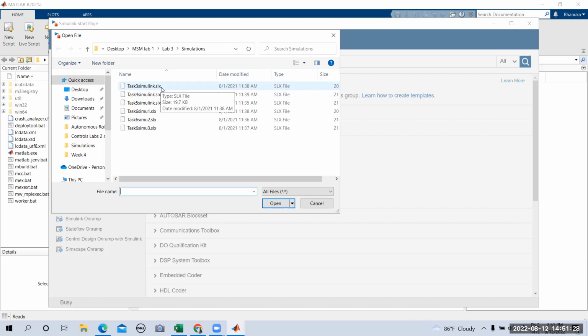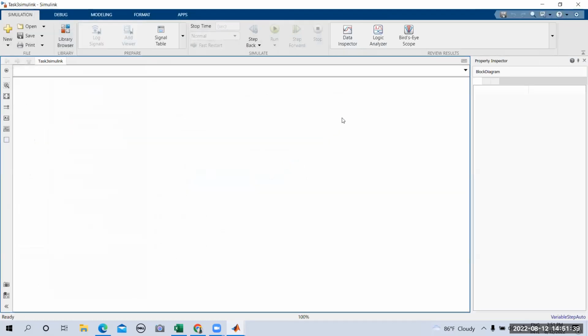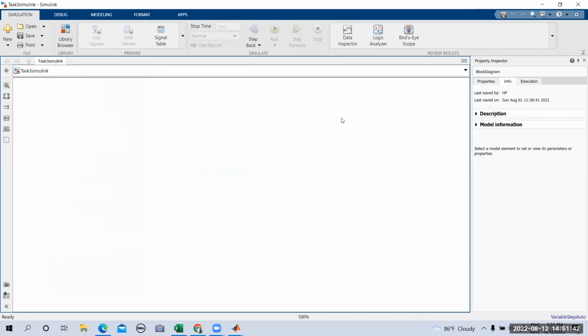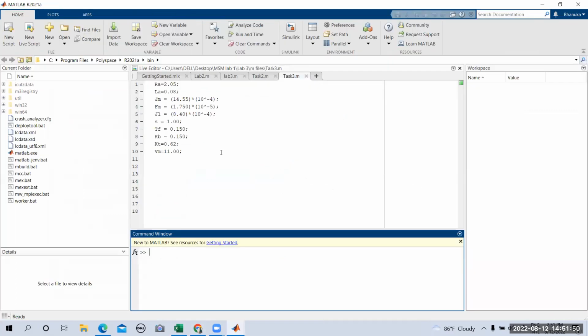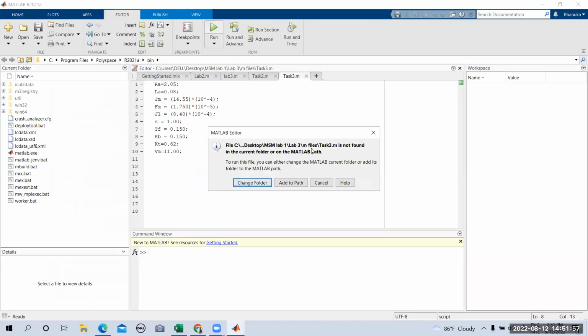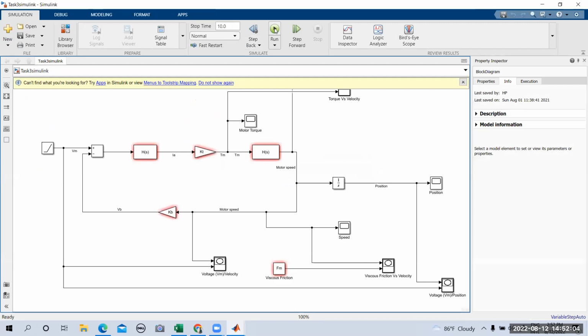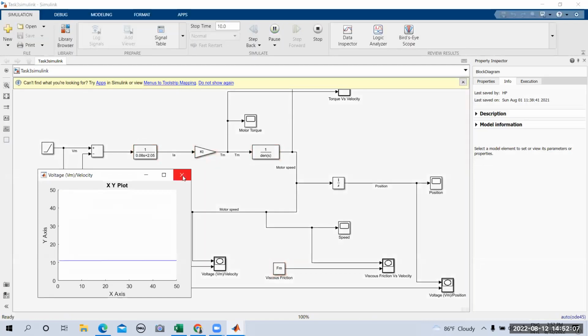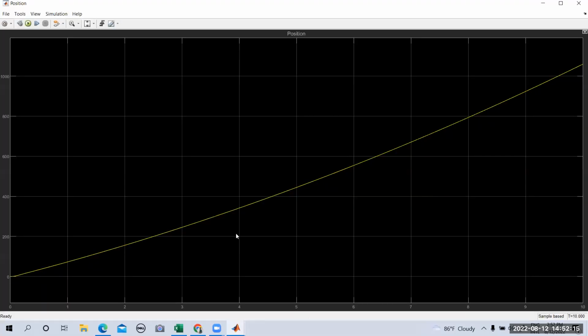where you have to model this. This is an example of an unsimplified model. For an unsimplified model, you have to derive the variables in the MATLAB script. So I will run this. See here, if you go here, you can run this and see the position variation, right? This is just the model, so you can see the position variation with time.